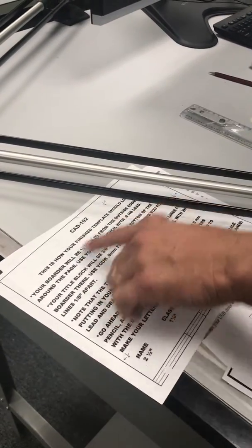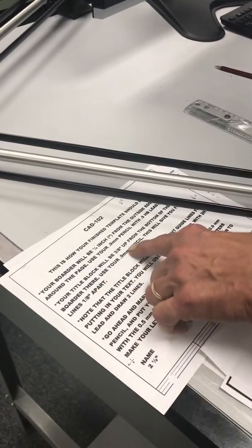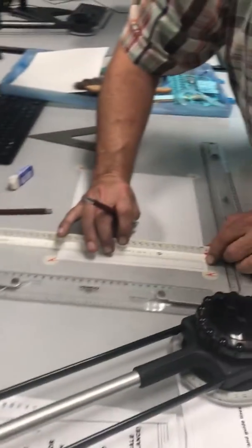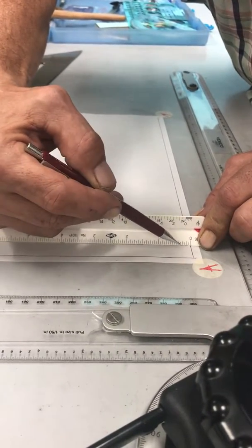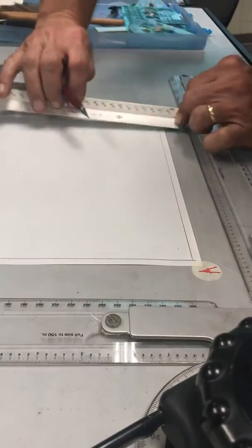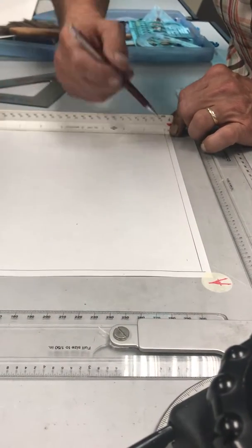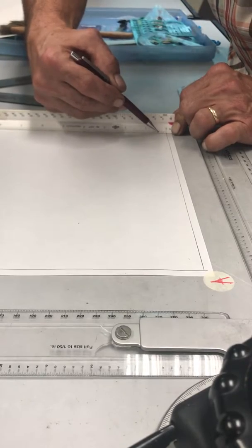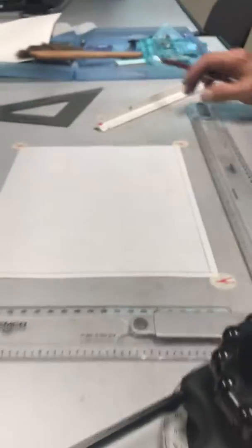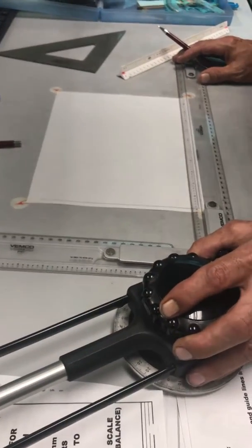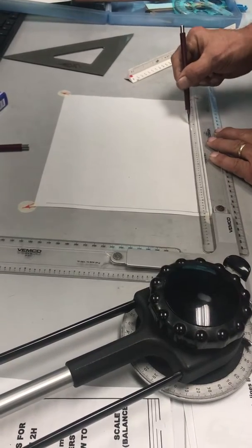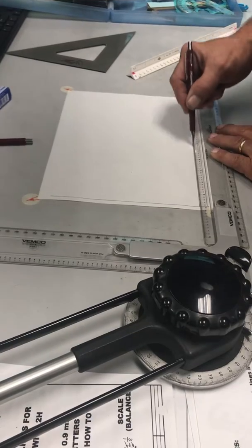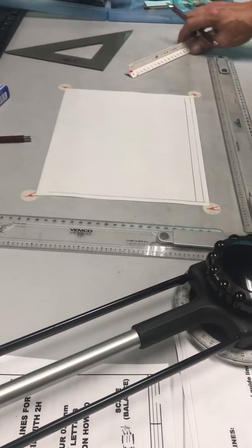All right. So once you do that, I'm just going to draw half of this. We want this to be, see, 1/4 of an inch from the outside of the border with the 0.9 and 3/8 up from the bottom. So I'm going to put this here. I'm going to go 3/8 this time. So that's 1/8, 2/8, 3/8. So I'm going to go right here. Same deal here. I'm going to take my 0, put on the line that's there. 1/8, 2/8, 3/8. So that's going to be the top of my title block where we put our annotations, all right? So I'm just going to go ahead. Notice that I'm not pushing, I'm pulling, and I'm twisting my pen at the same time, okay? There we go. Now that's the top line.